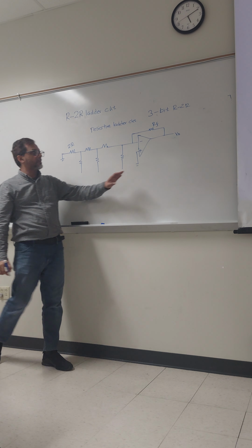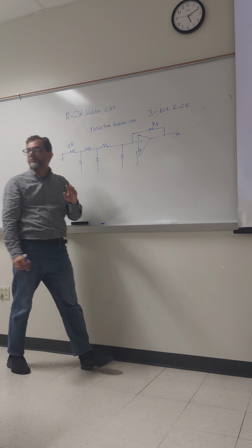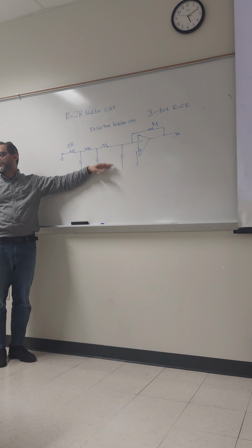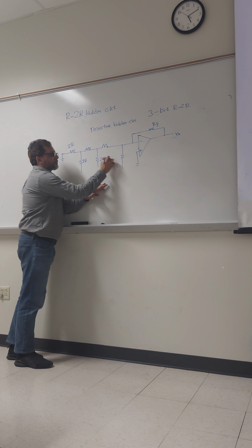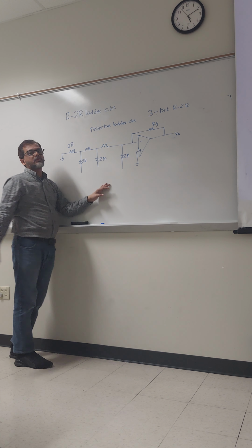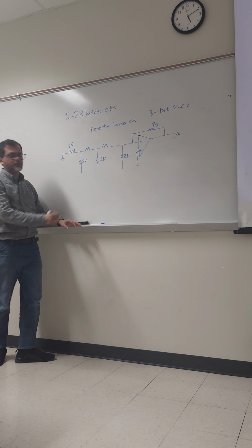Now, as I mentioned that it is a 3-bit R2R ladder circuit, these 3 bits will be given through these resistors, and these resistors are all 2R. That means we will give the digital inputs through this 2R resistor. Okay, through this 2R resistor.